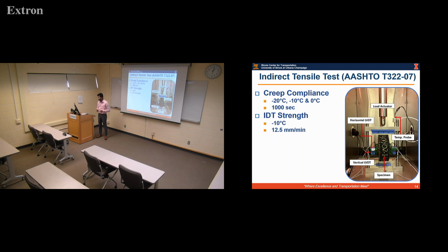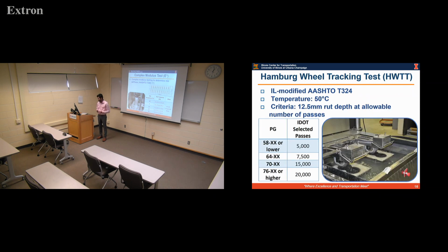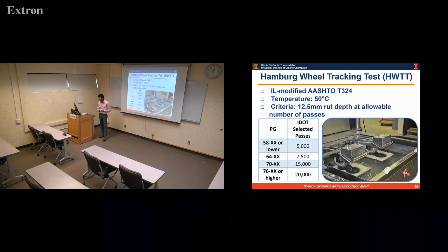this particular presentation. So IDT was one of the tests which looked into the creep compliance and the master curves of the creep compliance, which gave us the stress relaxation potential of the mixes, followed by the IDT strength test. The complex modulus test was conducted to determine the stiffness of these mixes, and a variety of test temperatures and frequencies were tested for the plant mixes.